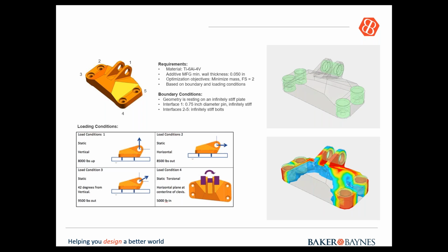The red, you can see there, the red is more or less almost everywhere where there's circles or openings. It does not mean that your bracket or your design will break. It just means, and it shows you, that is the points or the space on your design or on your part that is the weakest. So blue means your part is the strongest there, and the red means weakest. But it does not mean it will break.